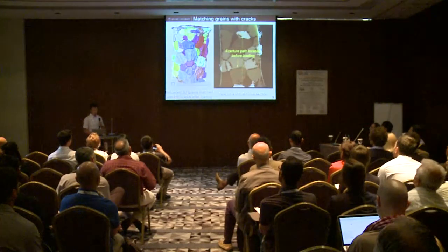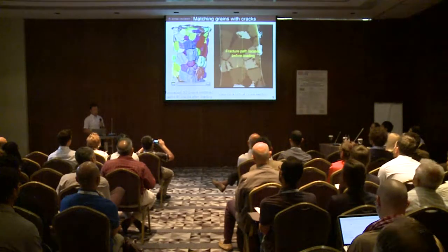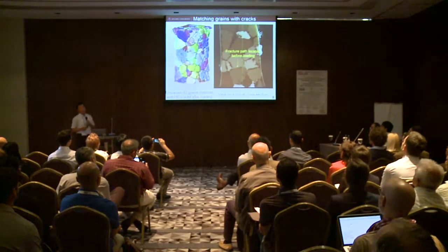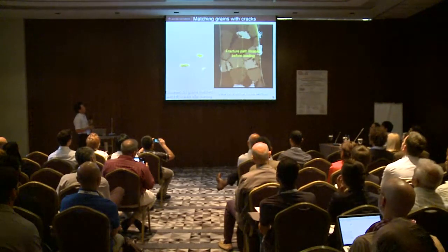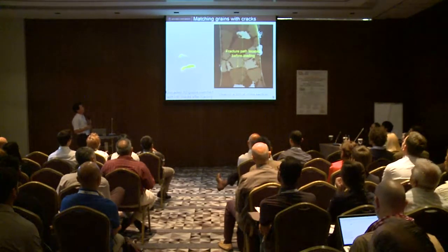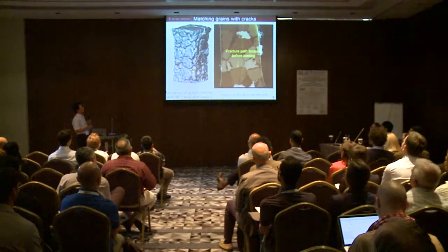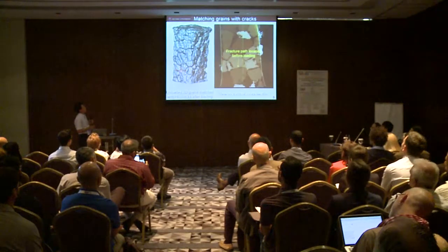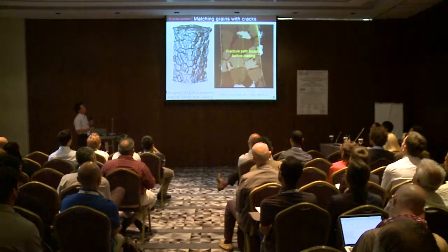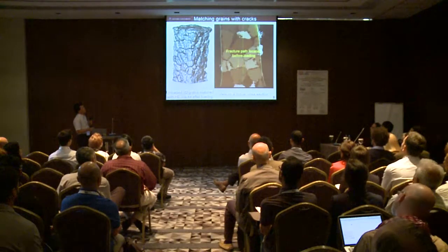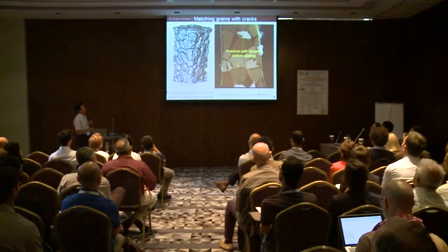So we are now looking at the reconstructed grain structure at the initial unloaded state. It has been reconstructed quite nicely in this way. And we are now looking at 3 initial cracks, hydrogen embrittlement cracks, which can be superposed onto the grain structure in this way. You can see a quasi-cleavage crack here, and also an intergranular crack here. If you take a look at this grain section, then you can see there is an intergranular crack here, which matches quite well with the crystallographic texture of the unloaded state.